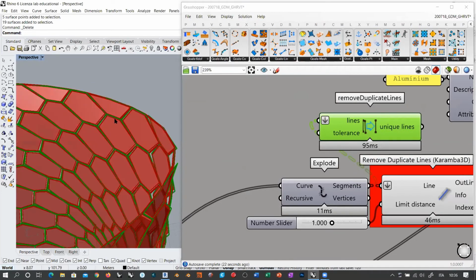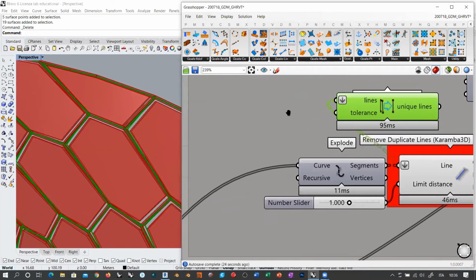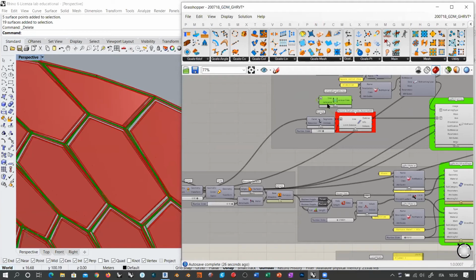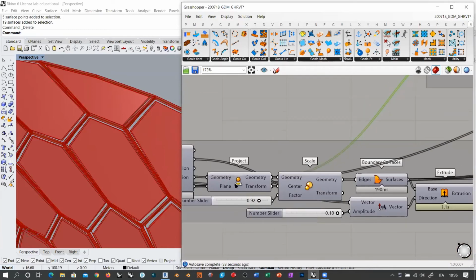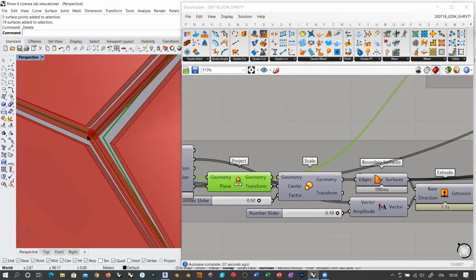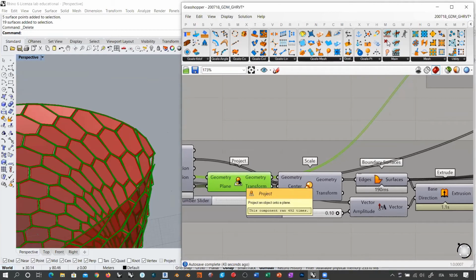The reason why this happens is because we have some tolerance control. Remember that in this case, I am using as the original curves the already projected curves. So there is this, let's say, deviation between the frames, okay? And I don't want these frames to be twice the amount because I have this deviation. I need just one mullion between two panels, okay?